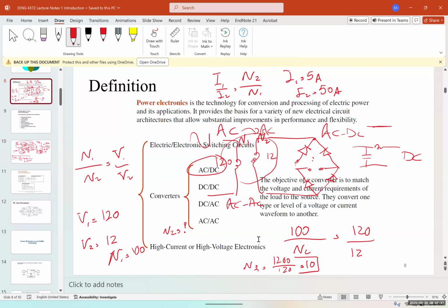So in this scenario, the amount of current we take is determined by the load resistor. Now, what happens if, and this is a great question, what happens if you accidentally short circuit the load? Most of these chargers have a protective system in them. If they have an electronic control system and the current surges, it's going to cut off the power.